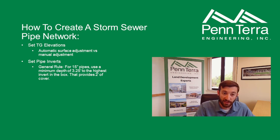So the next step would be setting top of grates. There's a couple different ways to do that. You can use the surface, or you can do them manually. Typically what I like to do is put spot elevations where my top of grates need to be ahead of time, and then I set them manually. I like to do it that way so that I can guarantee they won't accidentally adjust themselves if I change the surface. I want to be able to have control over what those tops are. If that means I have to take an extra 15 minutes and manually reset some tops when I adjust the grading, I would rather do it so I can be sure they're right.